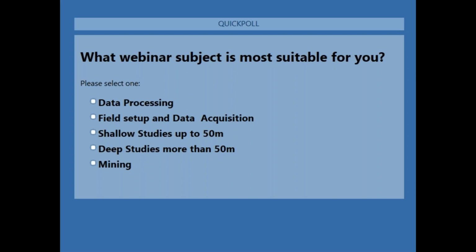But in marine studies, it's recommended to use 375 or 400 volts in the external transmitter, with high current output, like 10 amperes, 20 amperes, 25 to 27 amperes. So let's consider 400 volts, 27 amps, when I use the SuperSting 10 kilowatt.